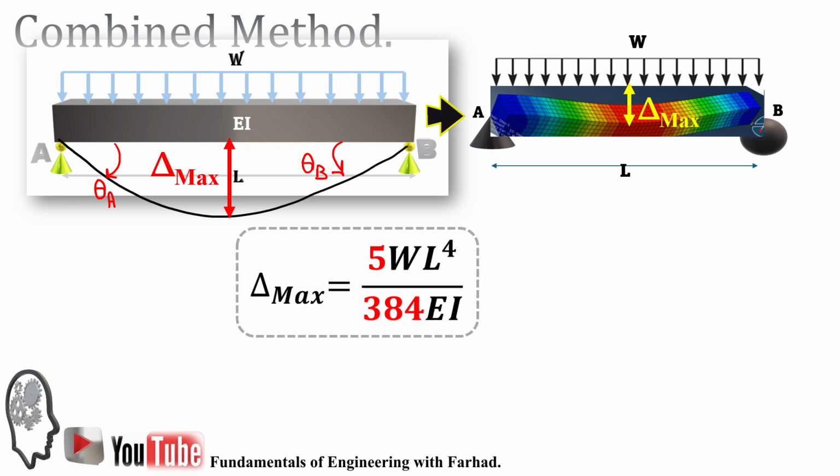Delta max is 5WL to the 4 over 384 EI and downward, and theta A is equal to theta B, which is WL cubed over 24 EI.